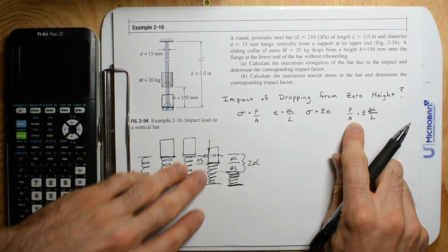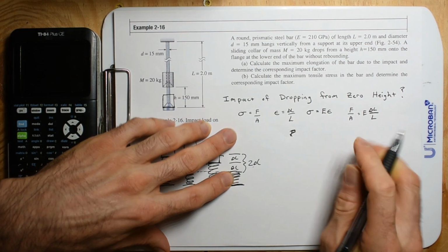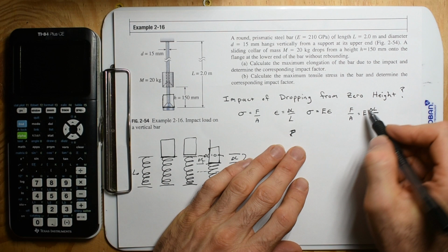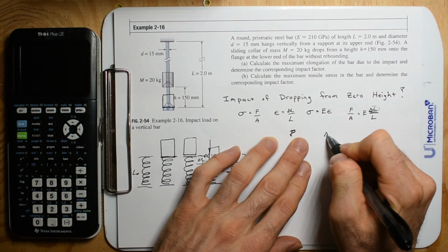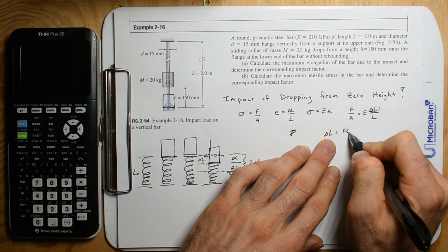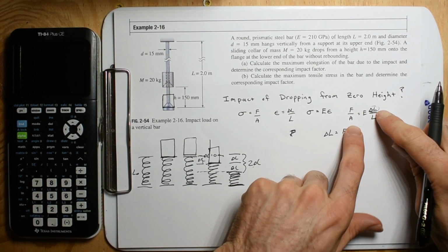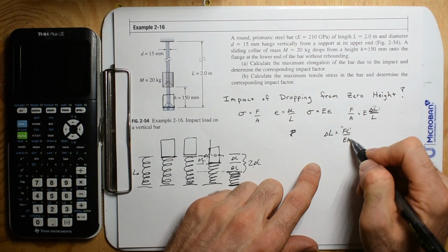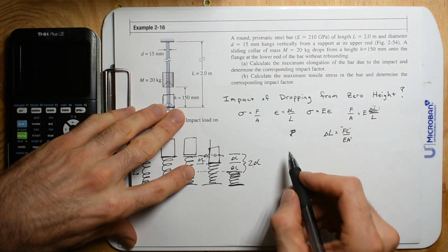And then what we want to do is rearrange this for force. I'm sorry, no. We're actually just interested in change in length, so let's go for it. Change in length, and this one's pretty easy: FL divided by EA. The L goes up top, the E goes downstairs, and maybe it spells flea, going that way. But hell yeah, so we can find that initial change in length.